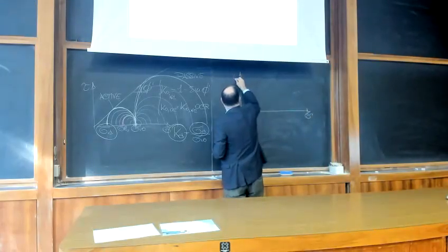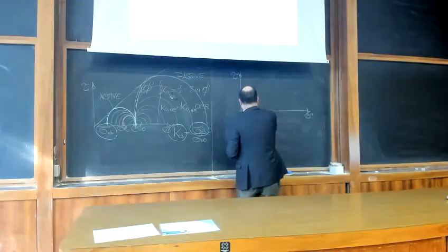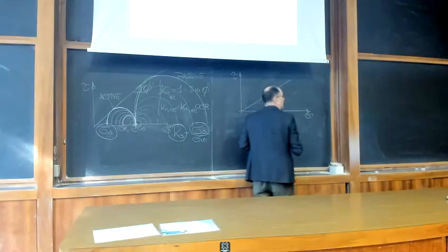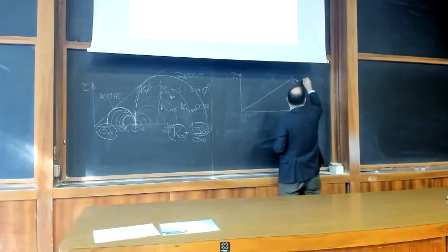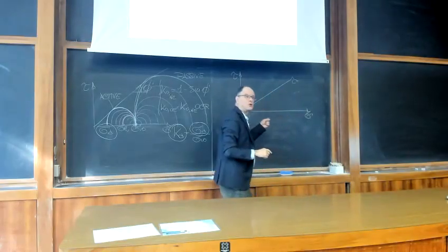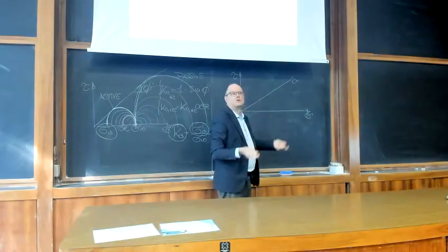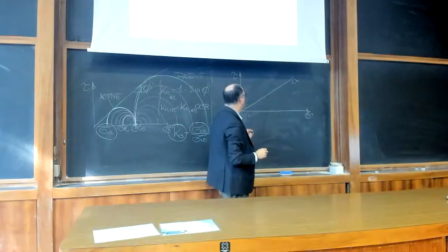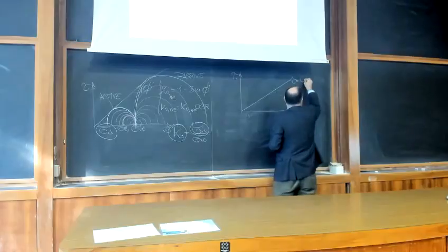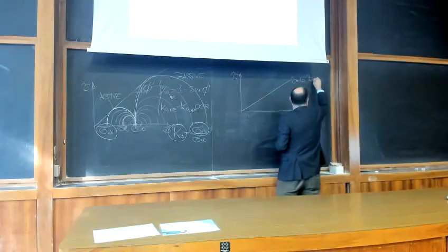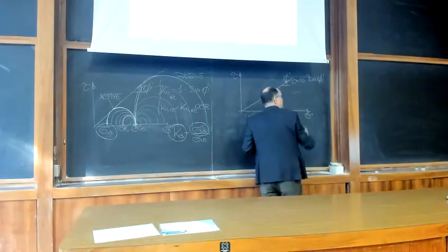Sigma dash and tau, we are in the Mohr plane. And you have a straight line, which is our limit line defined by the Mohr-Coulomb criterion, that we assume for a cohesionless soil, but it can also be extended to a cohesive soil. For a cohesionless soil, so no cohesion, the limit line is defined by sigma dash times the tangent of phi dash, and phi is the angle of our straight line.